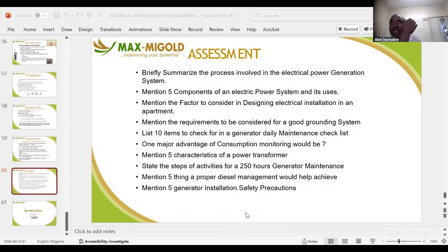The possible ways that electrical equipment can go bad are mostly earth leakage, electric shock, and naked wires bridging together. It will result in high voltage and will burn your equipment. So how often do you maintain your panel? How often do you clean your panel? They may say we don't need to maintain the panel, but dust is a resistance.